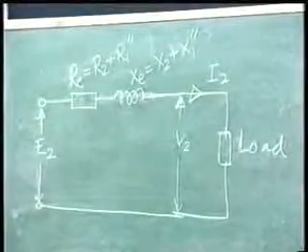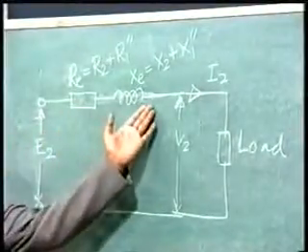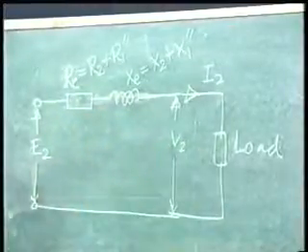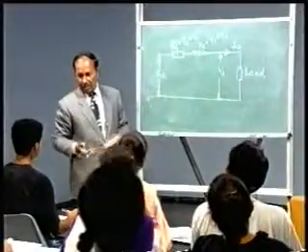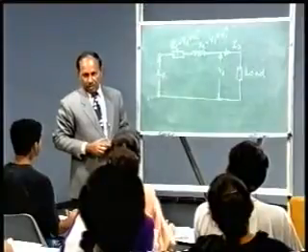And you can make any calculations of, like regulation, you can calculate what will be the voltage drop in the transformer resistance and reactance when it is loaded, so that you can calculate the percentage voltage drop. That is called regulation of a transformer. Have you got any question?